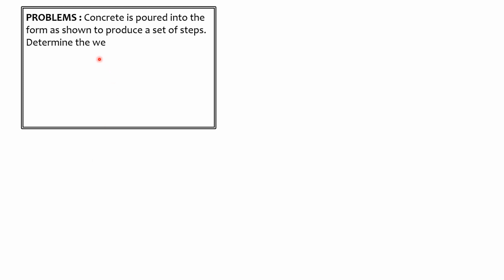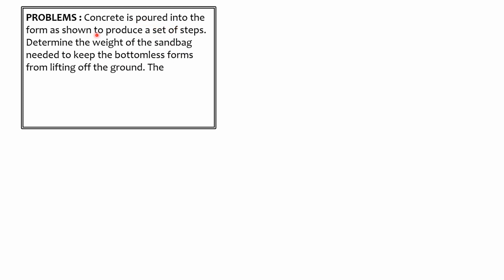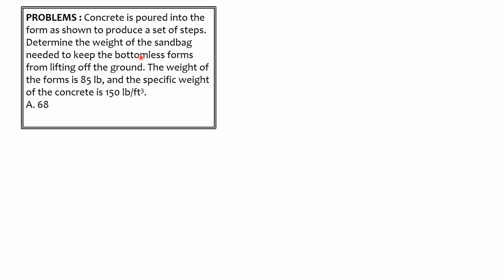Okay, let's proceed to the second problem on the application of pressure on curved and plane surfaces. So we use the concept of pressure on curved surfaces here to answer this problem. Concrete is poured into the form as shown to produce a set of steps. Determine the weight of the sandbag needed to keep the bottomless forms from lifting off the ground. The weight of the forms is 85 pounds and the specific weight of concrete is 150 pounds per cubic foot.